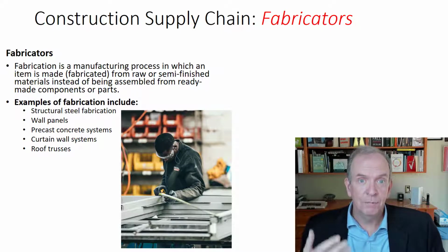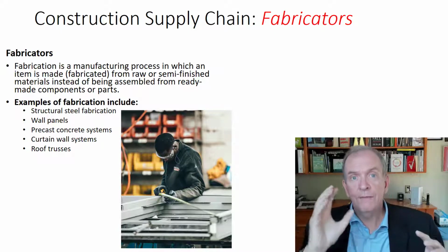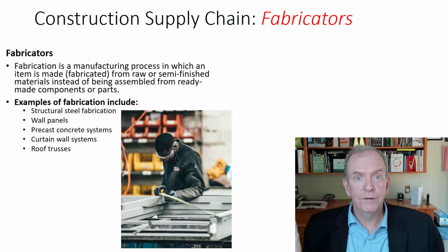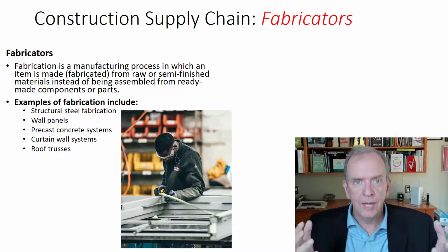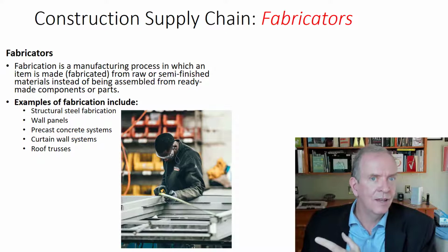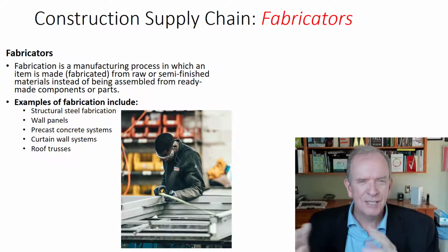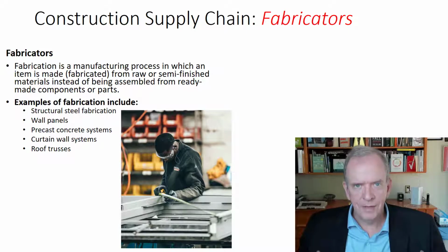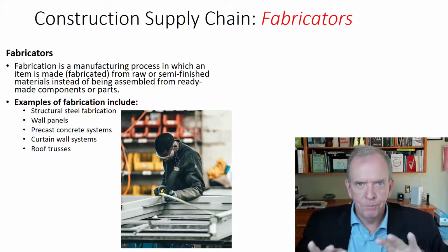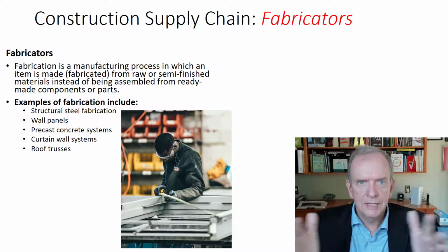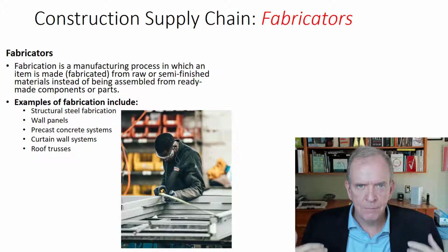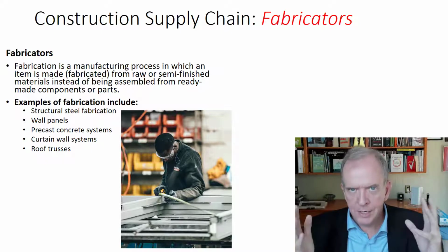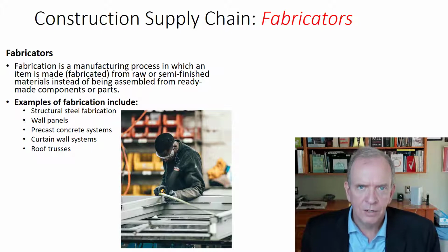So the advantage is in a BIM 3D model, you'd have the pipe, you'd have the duct, and you'd see there's an interference there, and then you'd collaborate to work out that problem so that you could prefab the duct ahead of time and have it actually fit. In the past, we've missed too many things. So that's some of the advantages that's coming along, and that's where we're going to see more and more prefabrication take place. That will allow us to have more things going on in the prefab shops and shorten the assembly time on site. So there is a big movement that way, and this ties very much with lean construction thinking, integrated project delivery models, design build models as well.